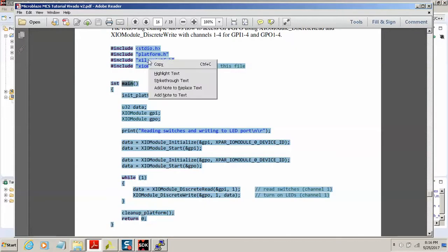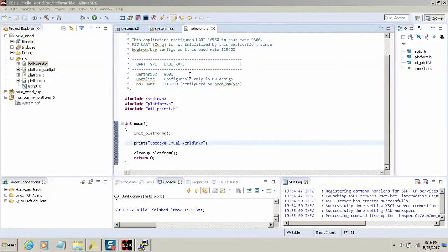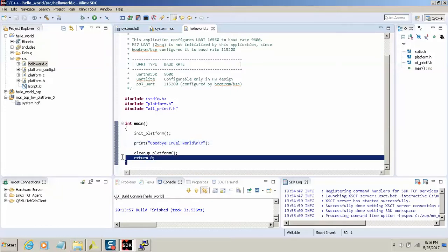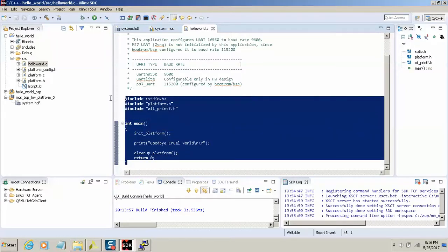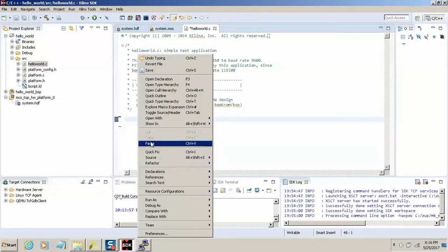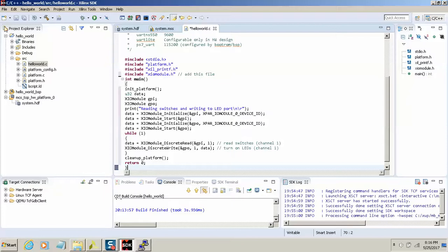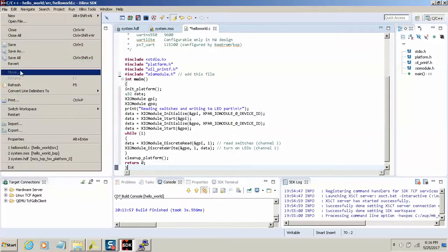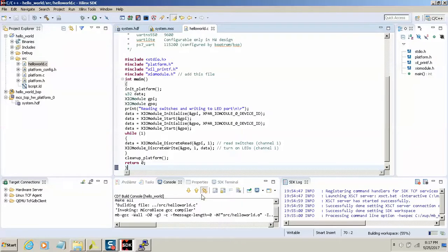All right, we're going to go back once again into SDK, and this time we're going to take and copy this section of code, which is a section on page 16 of the write-up. This will be our last little experiment, so I'm going to close this. And I'm going to basically take out the code for the whole Hello World endeavor here. I'm going to do a delete, do a file paste, again do a file save. And again, we see it's auto creating the ELF file.